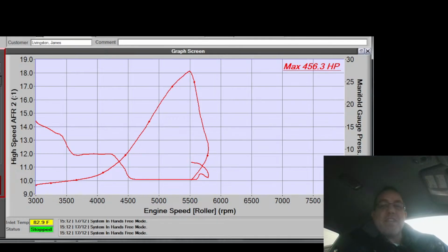Well, perfect tip-in, as in completely perfect, no screw ups and everything, is when AFR does not change during a tip-in event. So when you tip in, if AFR is flat and you let back off and AFR is still flat, that's perfect tip-in. If you get that, it's right. Now, does that happen on a Subaru ECU? Never. Absolutely never. Not at all. This ECU never has that kind of tip-in. Even stock, it doesn't have that.